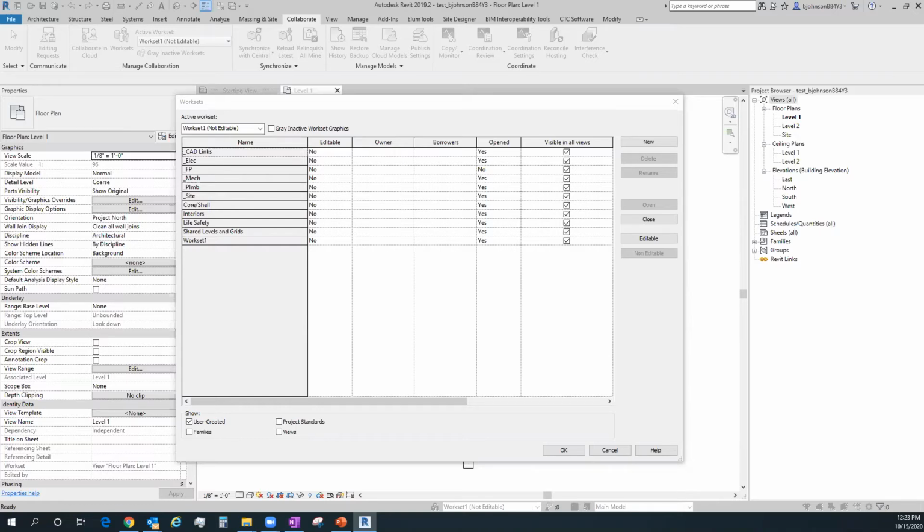For instance, if you've got multiple users creating 15 different sections per day, and it's two weeks later, and you notice that you've got 175 sections that are just section numbers, I would do the CAD cop thing and go and delete all those that are numbers that aren't actually named, right? Or it doesn't even have somebody's initials on it to tell me it's theirs, or they're going to reuse it or something like that.